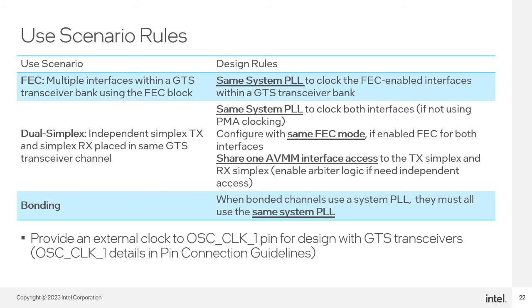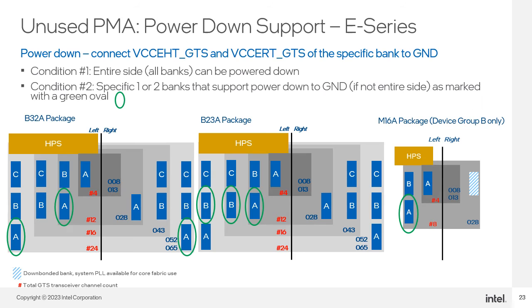If your design has a GTS transceiver, then you must provide an external clock to the OSC_CLK_1 pin. Here, we will talk about how to address the unused PMA. Intel Agilex 5 device has an ability to support power down. Let's start with E-series first.